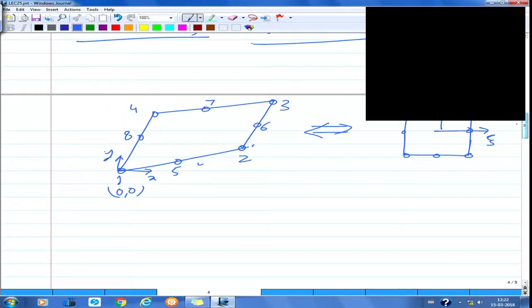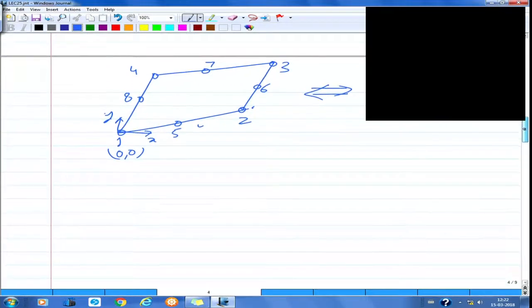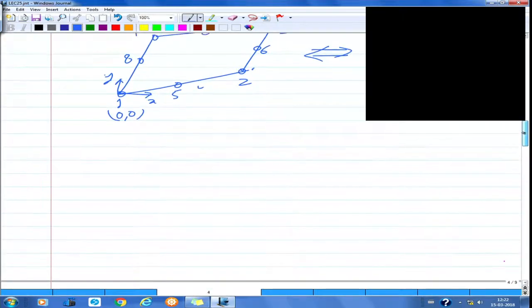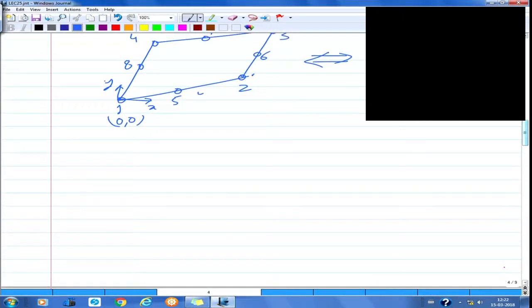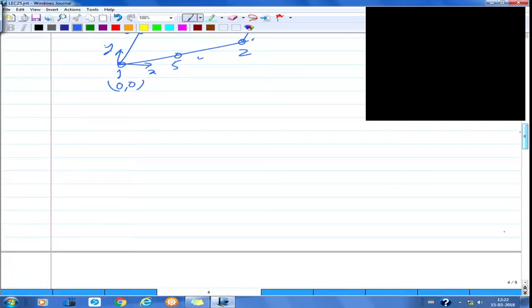Okay, so let us continue. You had asked a question at the beginning. The other question, I think, we will talk about when we take some examples. The internal load vector I had left in terms of ds, where ds is the element boundary differential length in the physical coordinate space. But since the quantities you are integrating are functions of xi and eta, ds also has to be expressed in terms of xi and eta appropriately. So you can write ds as the square root of dx squared plus dy squared, and then x and y are written in terms of xi and eta. Things like that we will have to do.